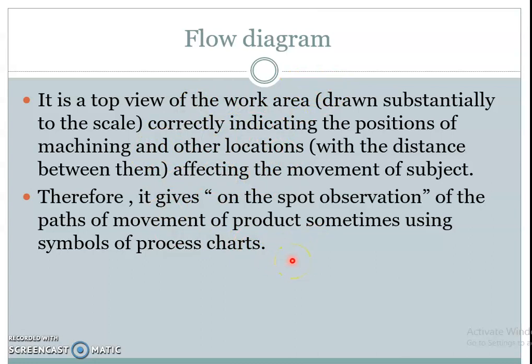These diagrams are very helpful to study the different layout plans and thereby select the most optimal layout, to study the traffic and frequency over the different routes of the plant, and to identify backtracking and obstacles during the movement.